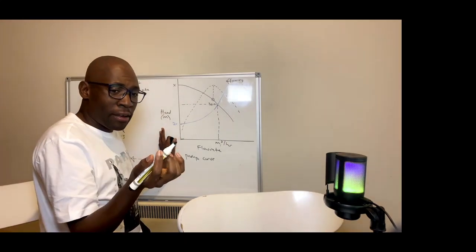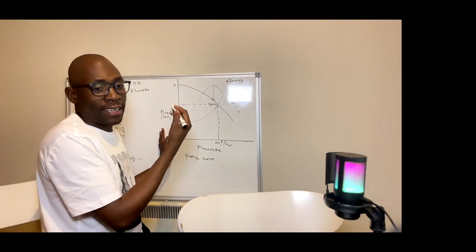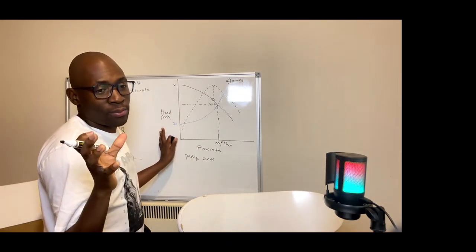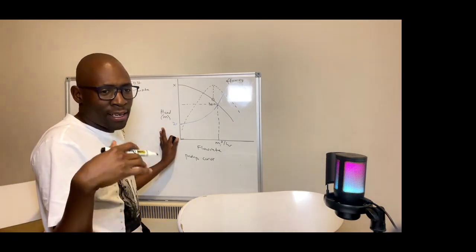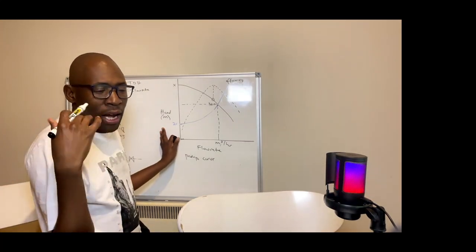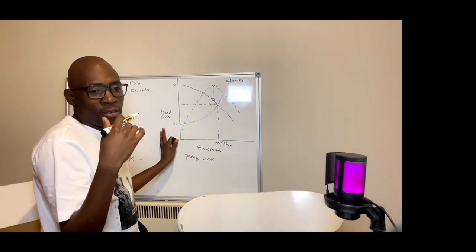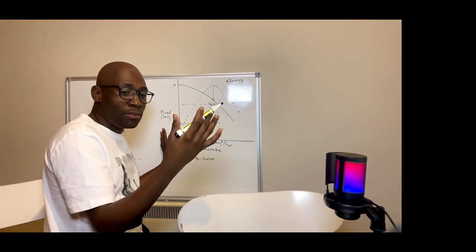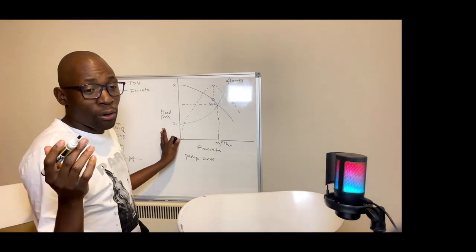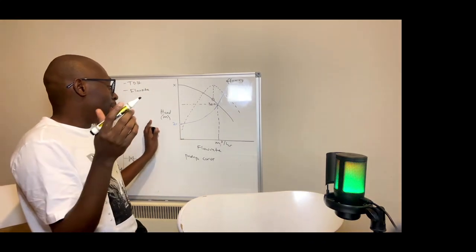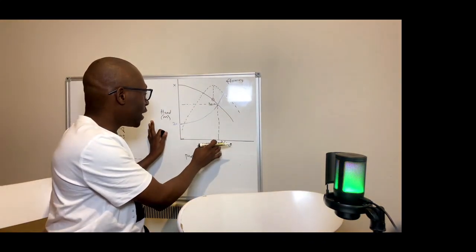The system curve is a curve that will be derived from what your system wants to achieve. In most cases, when people are sizing the pump, they'll simply say, I want a pump with a head of 100 meters and a flow rate of maybe 200 cubic meters an hour. So they can just come here and try to find those values.